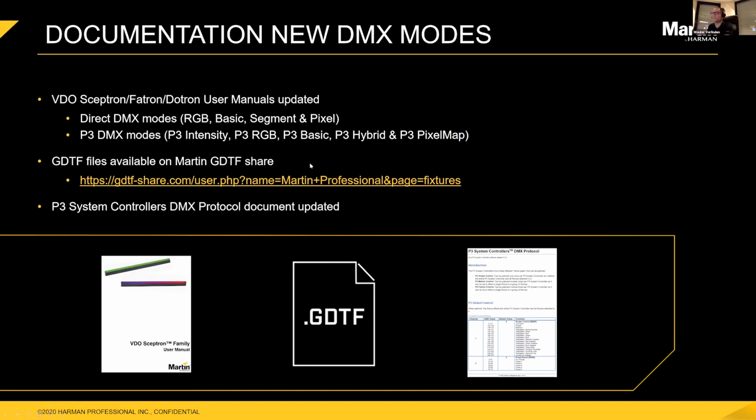Also for consoles, visualizers, and media servers using the GDTF format, such as the MA or the SHAMSYS systems, we have built Martin-made GDTF files for those fixtures, as you saw on the software earlier, that have all the new modes in there. So both the direct DMX mode, the modes when you run the fixtures with DMX straight from the console, the modes that have always been there. But in the same file, you will also have the P3 DMX mode, the DMX modes when you run the fixtures via a P3 controller, including the hybrid mode and the pixel map mode, with all the different possibilities